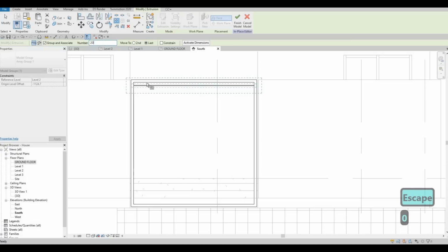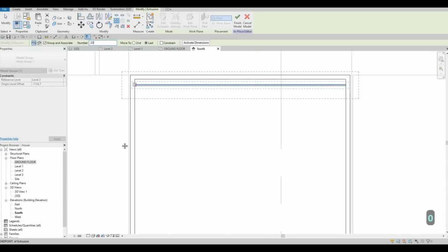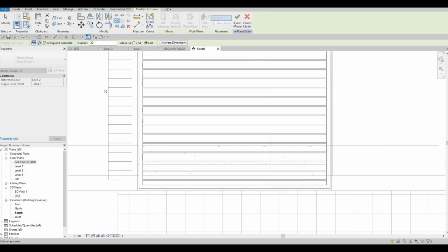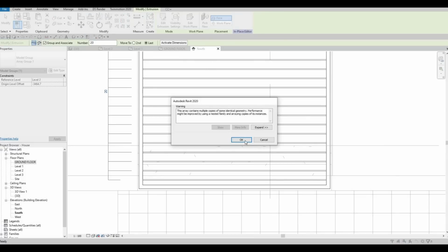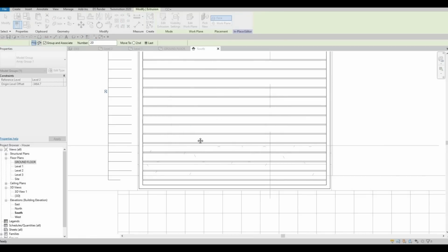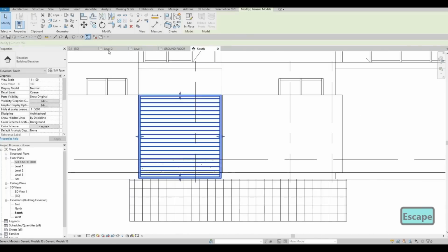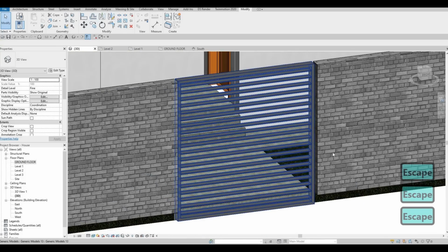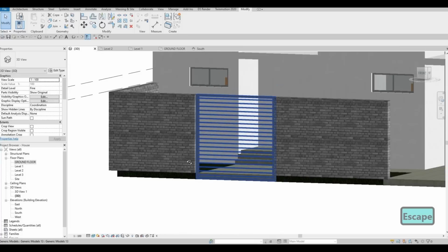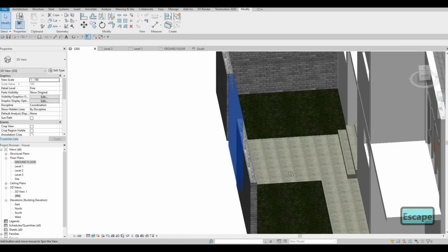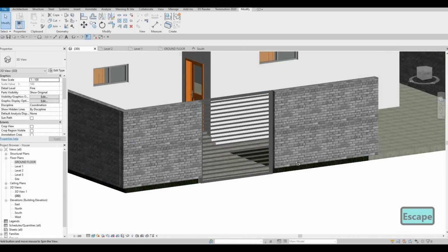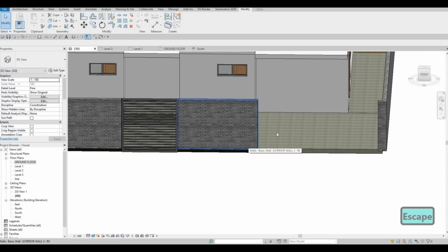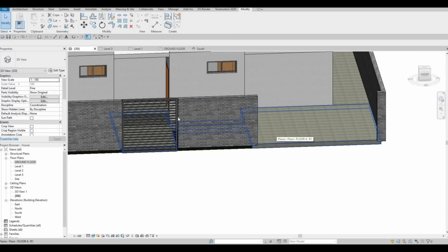I'm gonna put 20 and then last. I'm gonna grab it, and then I'm gonna put this one right here, and then let's click on finish first and press OK. Now if we see, it looks like this, and it looks much better, a different look, the slanted gate. Now we just need to create two more of this similar